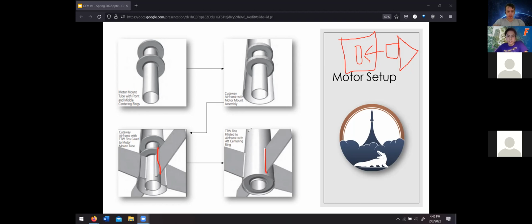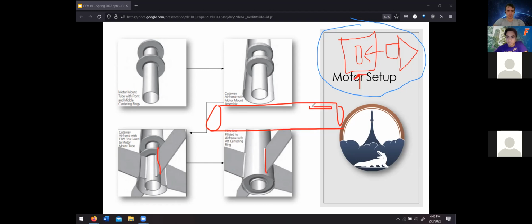So the way that we generally do fins is we do them through the wall, which is what TTW stands for. Through the wall mounting is the most used way of mounting fins. It's also probably the most secure way, because you have your circle airframe, right? And the purpose of through the wall fins is, like Alex said, you cut a slot through it. So you cut a small little excess where the fin can fit through the airframe, which is why it's called through the wall.